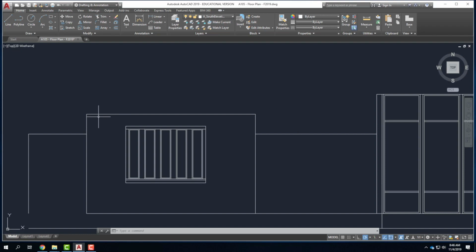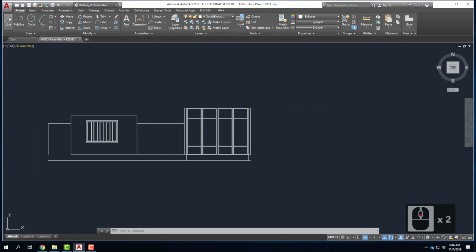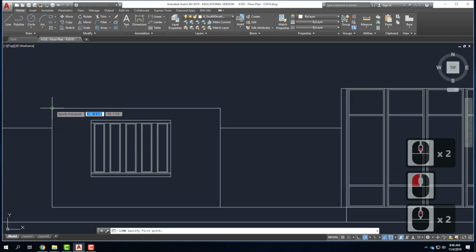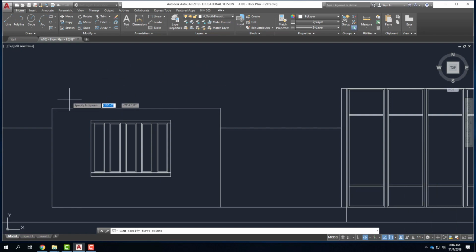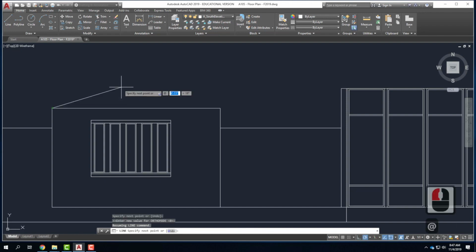And so this is going to depend on the look. So if we start with, say, a 6 and 12, I need to be able to go from this corner and know what 6 and 12 would be. So for me personally, I don't know what the angle of a 6 and 12 is. I do, but I'm not going to tell you the angles because it's something you have to keep track of. And instead, this is a perfect opportunity to use those coordinates, the relative coordinates. So I could say here, I want to go at, and then I just need a multiple of 6 and a multiple of 12, if that makes sense. So I could go at 12 feet in run, and